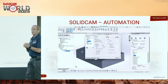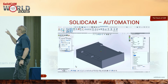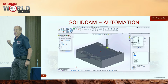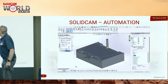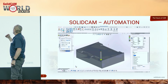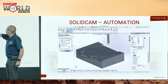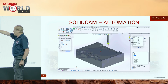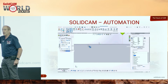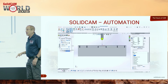Now, as I'm doing the simulation on the part, pay attention for a moment to the Z level. I'm going to start the simulation, and I'm going to stop for a moment. Note it's at 1.5 millimeters depth. Now, as it's going around, as you'll see, the depth will get further down, and then when it gets to its maximum, it comes up. Now, note, you'll see what happened over that boss. Protected it, didn't it? It protected it, and we'll see that in a few moments exactly what I'm talking about. As you see, as it's going down the side view, you can see how it goes deeper and deeper and moves itself away from the part, always keeping it.